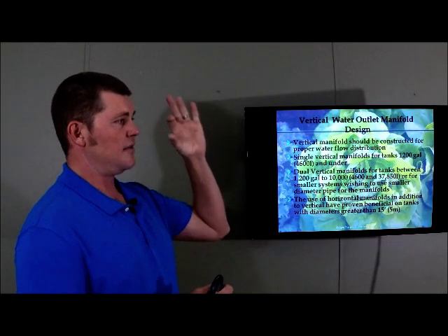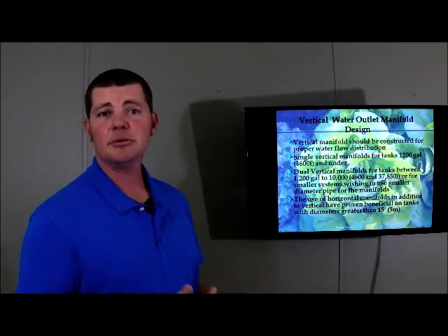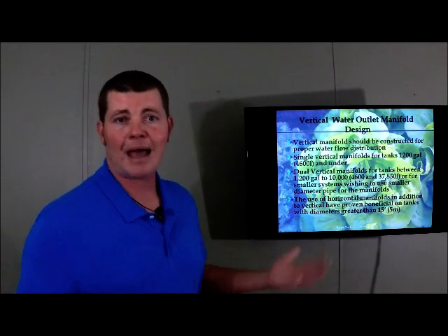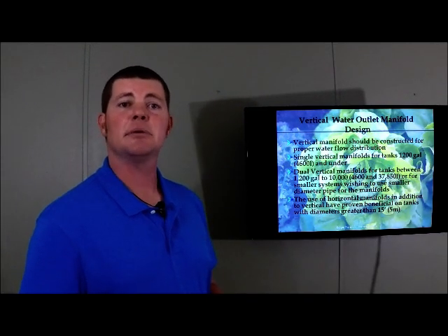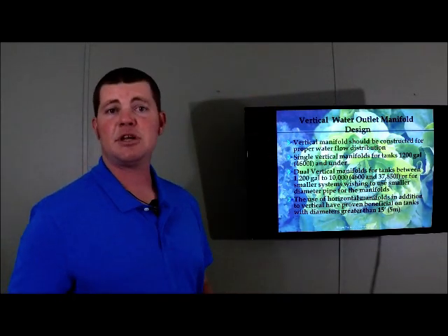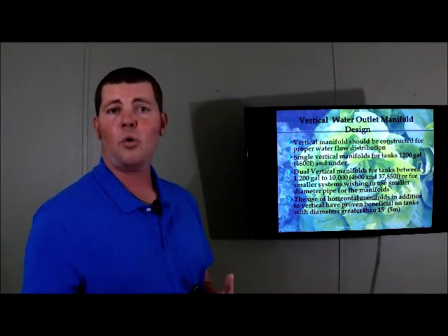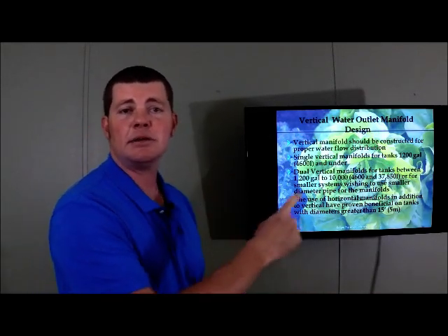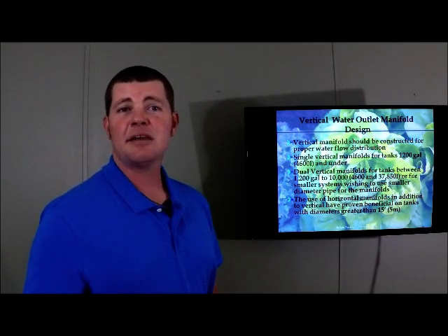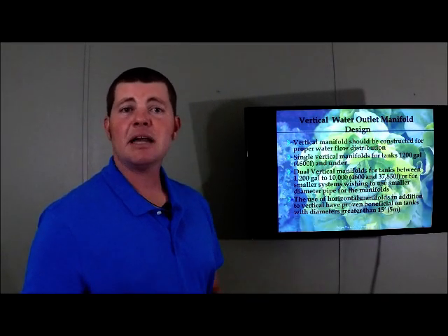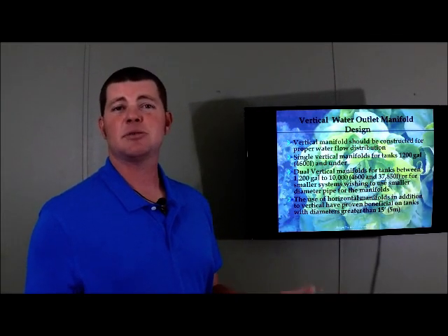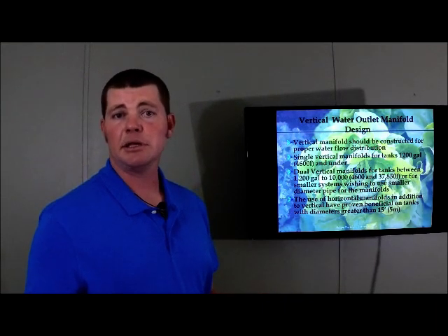So instead of water just having a single injection point, say at the top of your tank, which is very common to see in aquaculture facilities or just backyarders that are putting together a fish system, we actually want to take that pipe and bring it all the way down to the bottom of the fish tank. And we're going to drill equal holes so that instead of just rotating the top portion of the tank, we're rotating the entire water volume inside of that fish culture tank. And by creating that rotational velocity, it's just what we've been talking about this entire time. That's what allows these tanks to become self-cleaning.